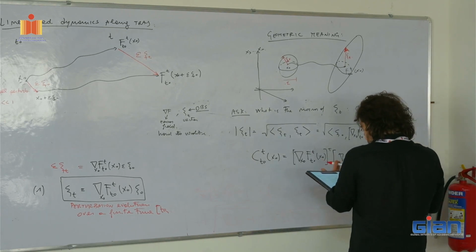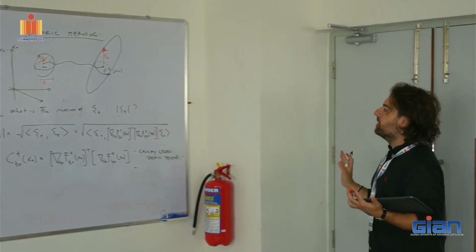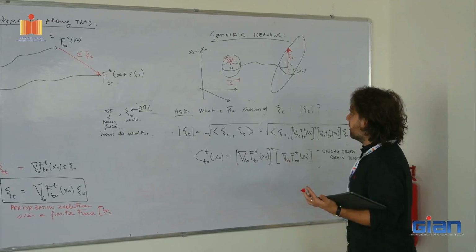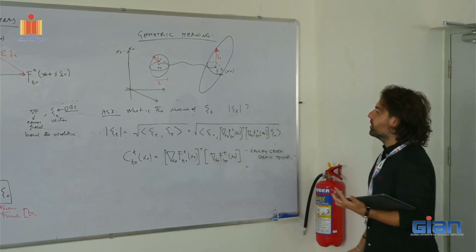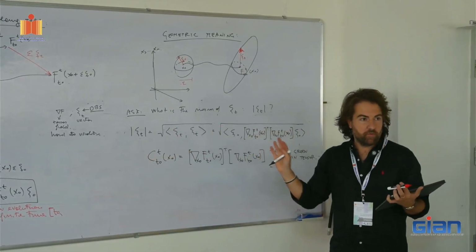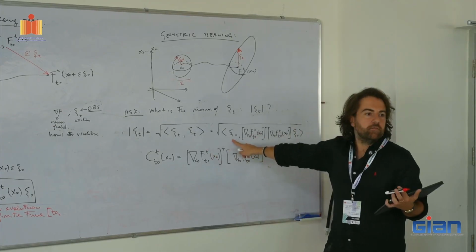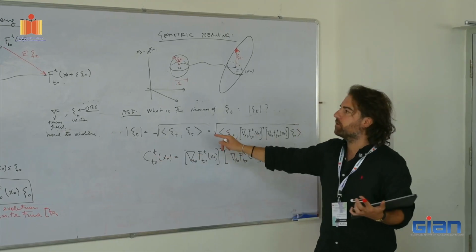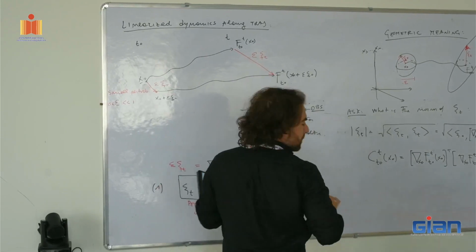So basically, there is dF there. Now I constructed a very similar tensor in this particular way. This is the Cauchy-Green tensor, and it is the tensor that is relevant if you want to understand the norm of zeta t. Now we're going to see how. Of course, you pick a zeta 0 and it's going to spit out a scalar from this operation. Pick the zeta 0 direction here, and it's going to tell you the length of zeta t.